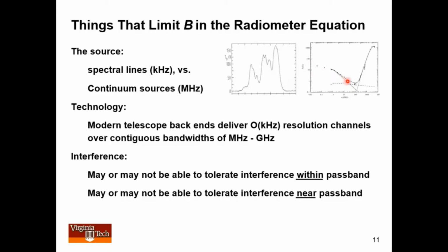You could really measure it anywhere, but where you measure it is going to tell you something about just that part of the spectrum. So yes, you could increase the bandwidth. You could measure this with 100 megahertz bandwidth, say, but as the bandwidth increased, you'd start to lose the ability to know what the spectrum looks like, whether it's going down, whether it's going up, or so on. So that becomes a limitation on B.